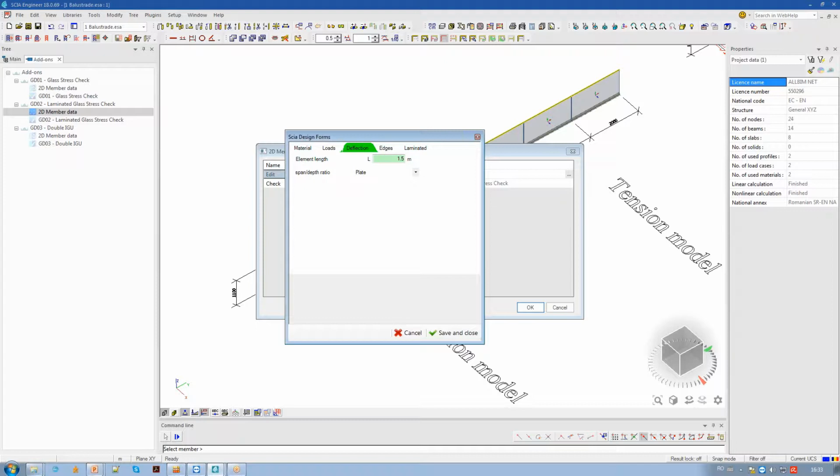And then for the deflection, there are different provisions to calculate the serviceability limit, and we need to specify the element type, and also we can input the element height. Why do you have to input it? Because when we model glass, in this module at least, we will go with shell elements. We can start with linear elements, but in the end we'll transform everything into shells. Why do we do that? Because as I stated before, we need to see what happens with the stress concentrators, exactly how the connection occurs and where they are present, because those are the points where the structure would fail.